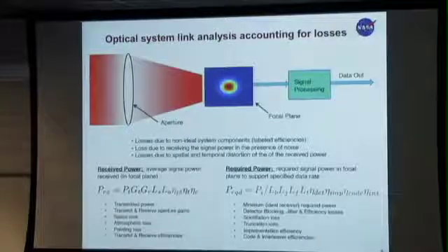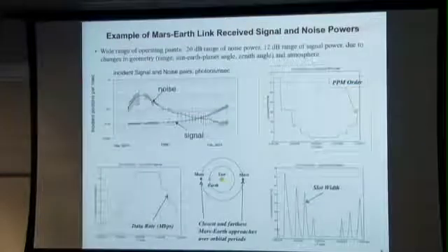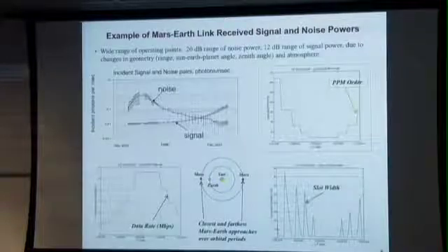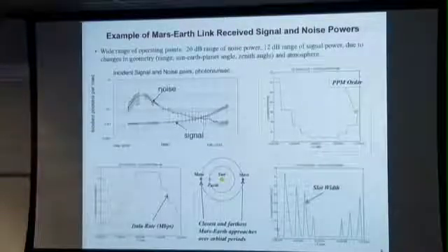The required power under ideal conditions would be something called P sub I. It's going to require a lot of math and models to determine what that is given the received signal. But whatever you calculate, there are other losses that govern that. Some of them are multiplicative losses, just like these are, but they're on the receiving end. So we have to account for those, and this talk will cover a good number of those, not some of the obvious ones like space loss and antenna gains.